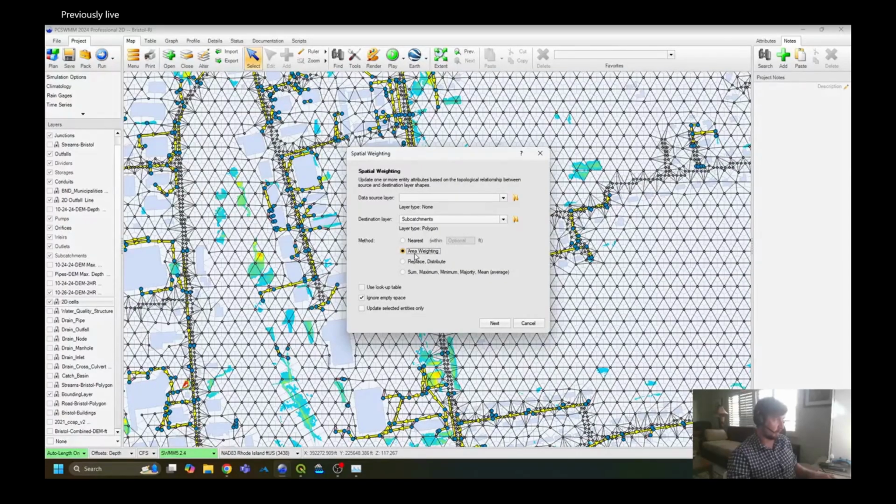It's actually a really nice tool. If I'm just building a model super quickly, I'll just try to create some reasonable infiltration rate just to test out to see if it's running. But if I start getting into the details, this is absolutely something I recommend including in your workflow, so you can start having more realistic and primarily justifiable infiltration rates in your subcatchment layer.